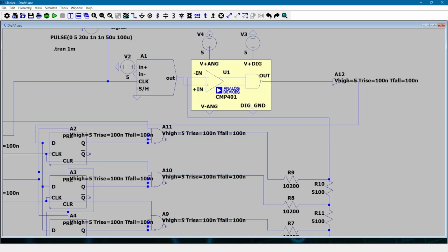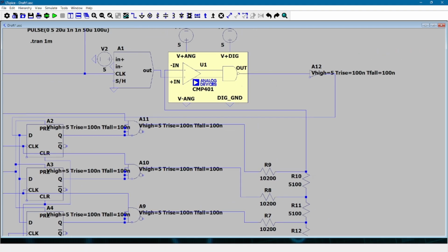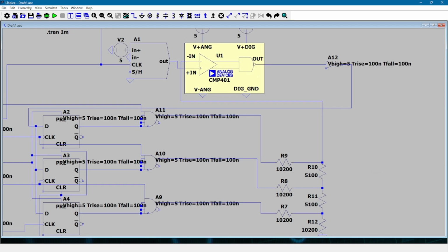And the DAC voltage is basically just a guess. It takes the previous voltage and then adds the next voltage, so it's an estimated guess of what the analog input is. This guess is generated based on the current bits. So if our guess is too big, we know that bit must be a 0, since anything with that bit will be too big. Then we guess again. Oh, this time it's smaller. That means that this bit can be set.